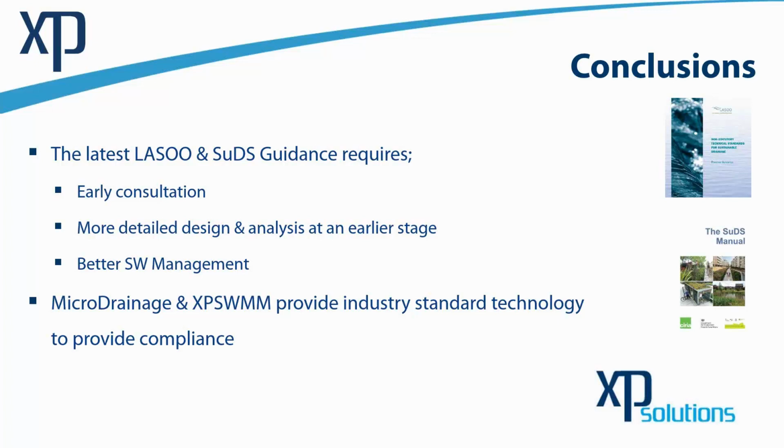Peter, I have a question from Ali. He was asking if the drainage system in the new development is considered. Yes, the model which we bring from MicroDrainage is fully considered, and if there is any capacity, it will take the water inside, right? And similarly, if it runs out of capacity, it will give the water back to 2D. So basically, anything which comes from the north, if it hits the new drainage system which was imported from MicroDrainage and there is capacity, it will absorb this water in, considering there is space.